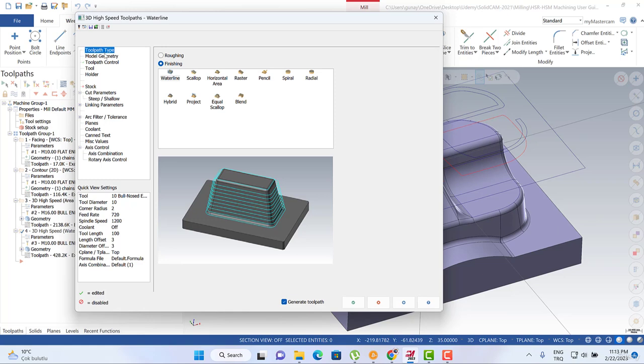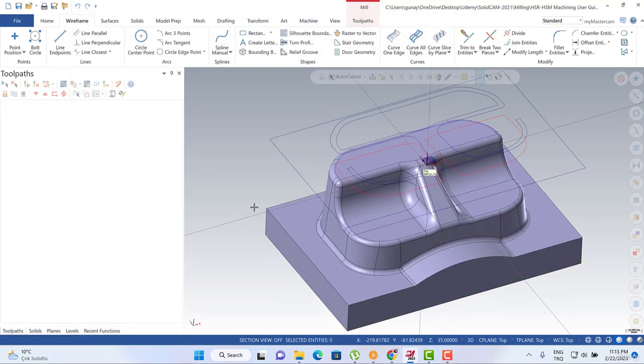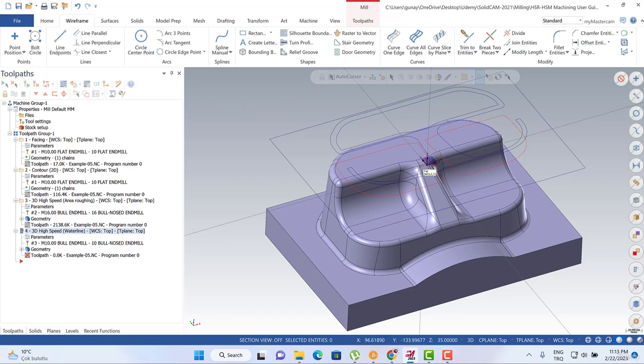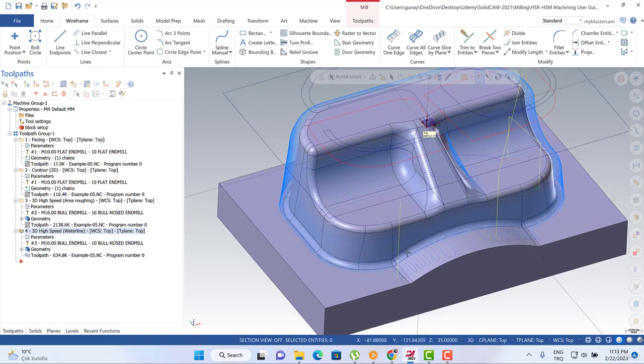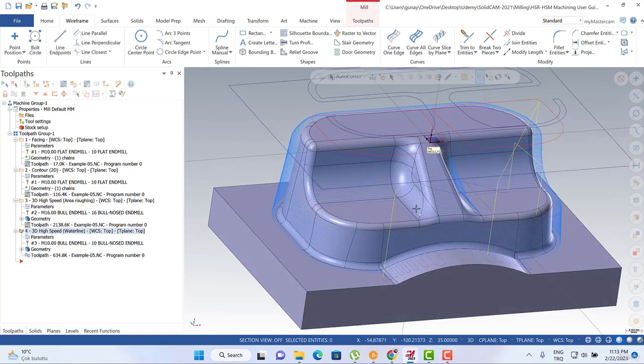And when we turn to the model geometry, we can also see our roughing and semi-roughing process here, 0.3 millimeter. I just need to make them 0 to 0, and then we can recalculate our toolpath. And after the calculation, we're gonna see that kind of toolpath. Okay, everything seems fine.